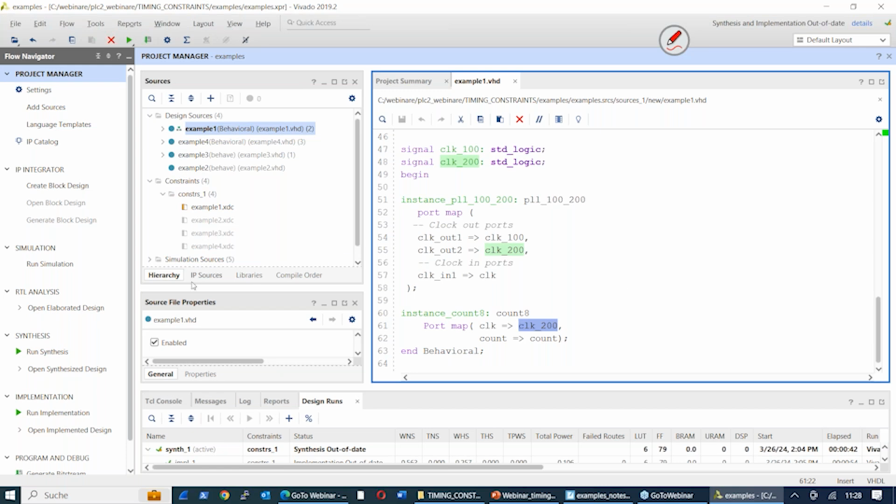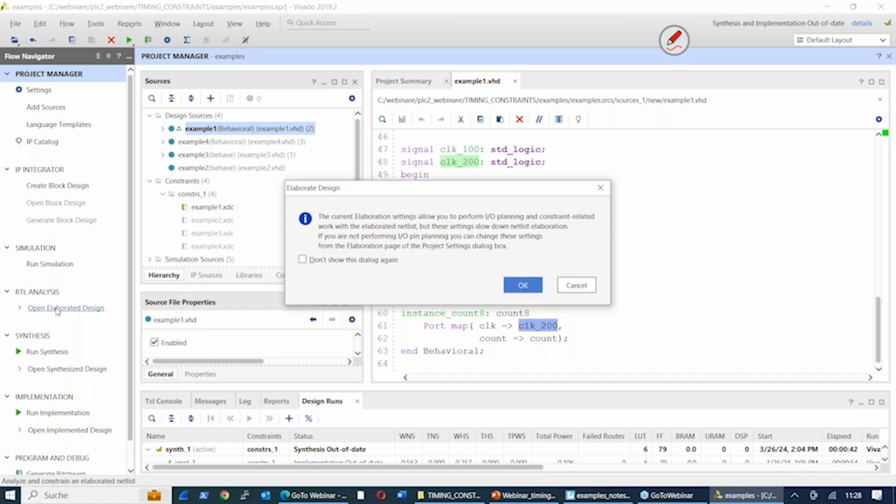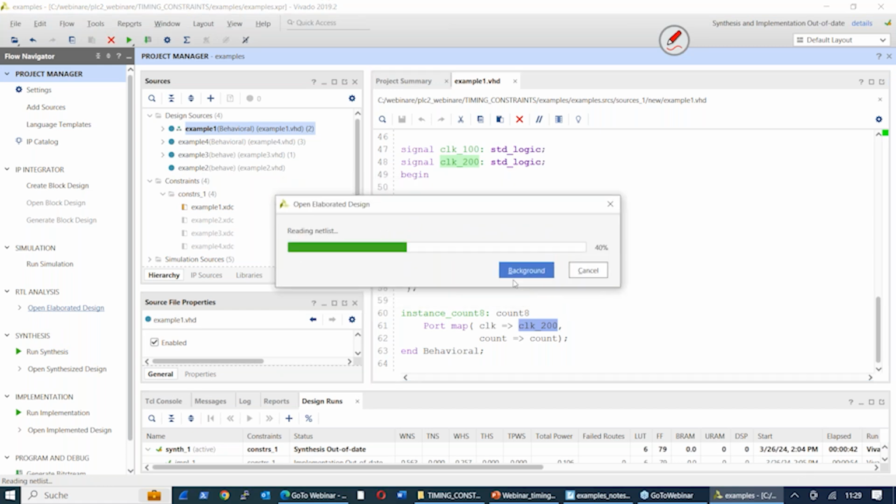Now, if I just run the elaboration here, then you will see the structure. And then if I actually run the analysis, Vivado will tell me first that there are actually two clocks in your system. Actually, it will tell me there are three clocks, because one is a definition of my external clock, and then two internal clocks. Even one clock is not used.